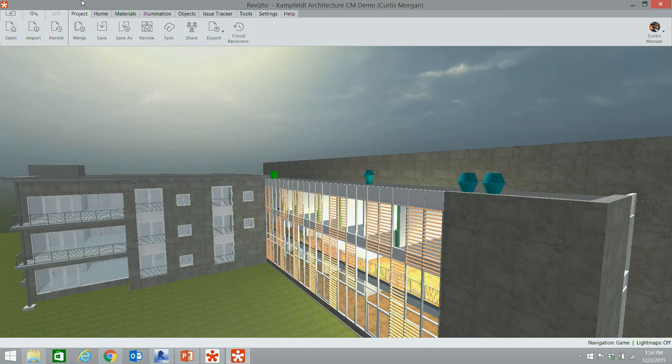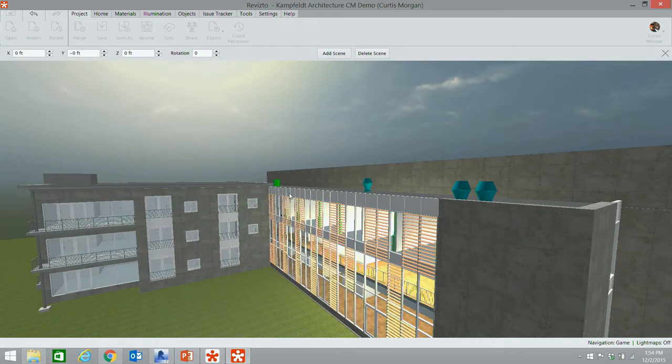You can export, and then we have merging functionality, so you can merge any different projects you have inside of Revizto, or during the export from Revit, you can also merge different files. And all these files come merged with the sheets attached to them, because a lot of times people ask, can we merge the sheets as well? So that's also merged during the export.